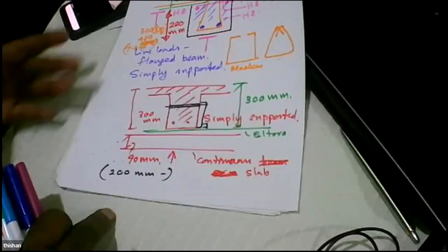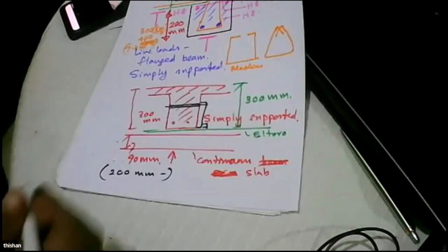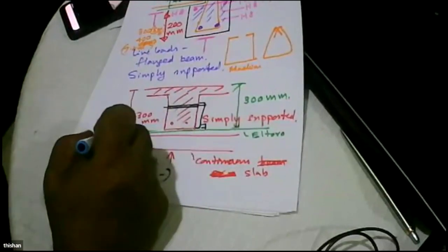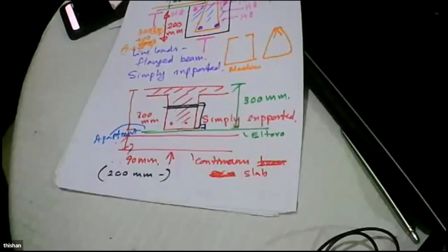If you think having a beam is not a major problem, then you don't need a ceiling. So basically in houses, we can have the beam exposed. But in apartment buildings, because you are selling the apartment, it is better to have a ceiling. Because you are selling the apartment, there will be a big task of explaining to the people why you have a beam. So it may be far easier to have a ceiling and conceal everything, and there will be a particular advantage because you can do all the wiring before the ceiling is completed, and all the wires will be